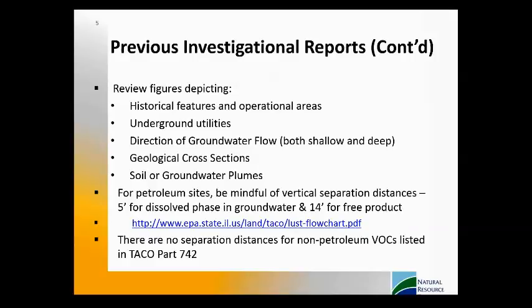Also, when reviewing figures, you're going to want to look for potential underground utilities, operational areas, and direction of groundwater flow. Geological cross-sections are excellent sources of information for the conceptual site model. And if there are soil and groundwater plume maps, those should be incorporated into your evaluation as well.